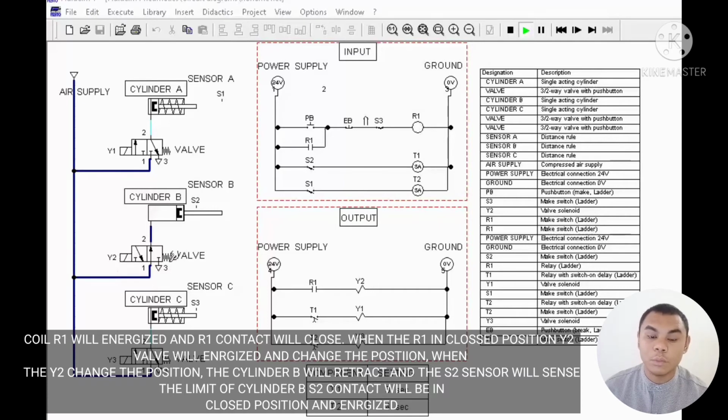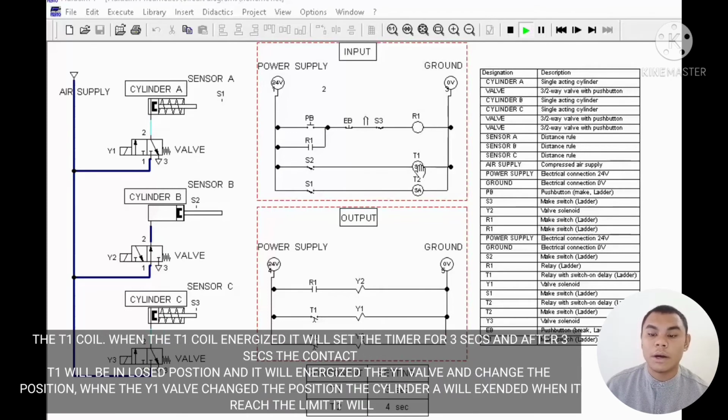When Y2 changes position, cylinder B will retract, and when the S2 sensor senses the limit of cylinder B, the S2 contact will be in the closed position and energize the T1 coil.